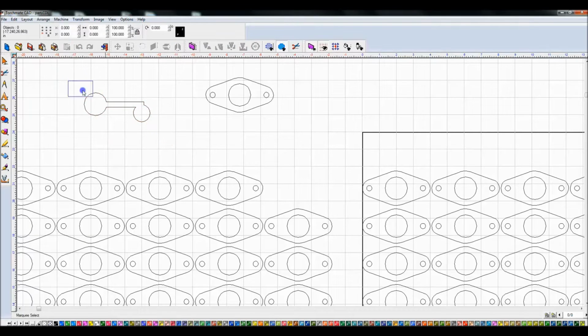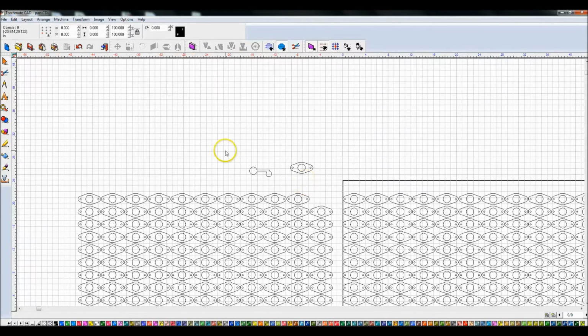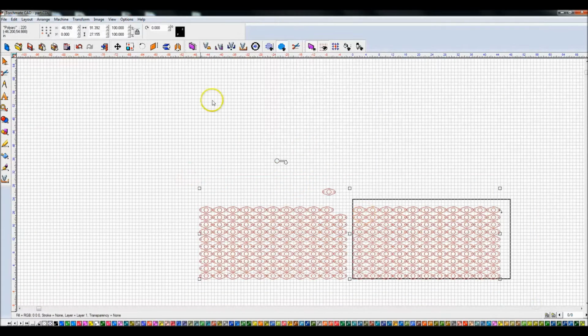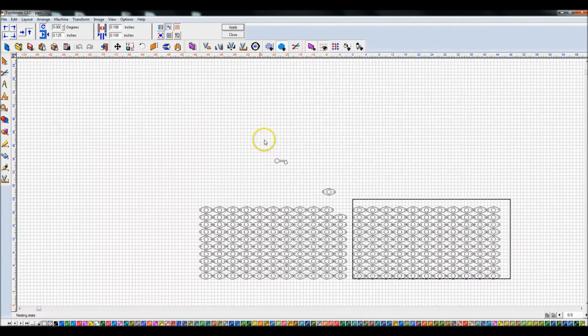There we go. Okay, so now if I mirror this in any direction, you can see that this is what it's talking about on the mirroring. So let's keep this part off over here just in case we need to use it again during this and explaining this. So go back to the nesting. Do you want to allow parts to be mirrored? Sometimes you can't, sometimes you can. In this case I can, so I'm going to say yes by clicking it.